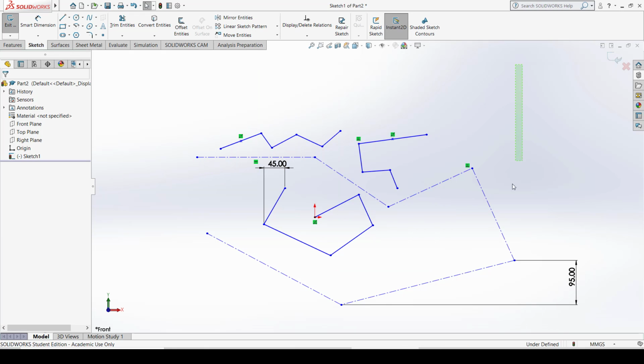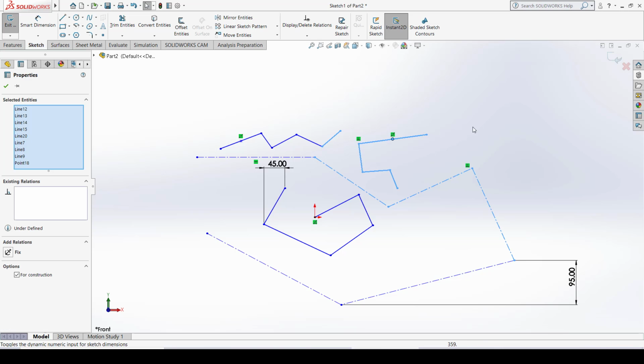The previous window is green in color. You can see here it has a dotted outline with green color, and if your window is dragged from the left hand side of the screen, you can see it appears blue in color, and the boundary of this window is a continuous thick blue line. Now what is the difference between these two selection windows? The first one is the window where you drag the mouse and just touch the element with this window. That element is selected, whether the element is fully inside the window or only a portion of it is touched by the window. So that means when your green window touches the element, it selects the whole element.